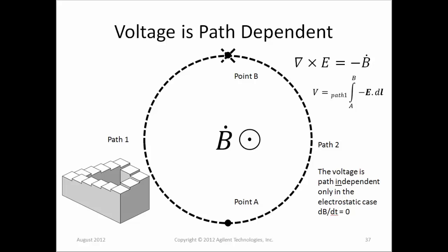The nice thing about S parameters, of course, is that because we're measuring these power waves, we avoid the need to measure specific voltage and current. We measure the power at the measurement plane, and that gives us a well-defined measurement.